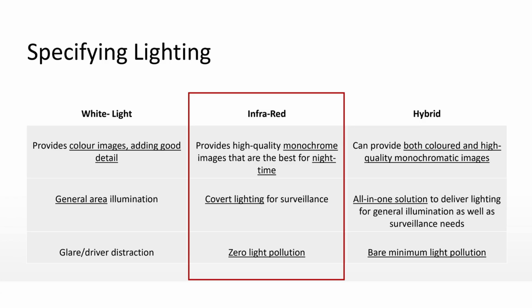And so you'll often see about a 50% drop off in terms of usable distances. However, where this comes into play is, of course, applications where no red glow at all can be required or allowed. So, for example, we'll commonly see this in train line type applications where the red glow, even just a very faint one, could be construed as a warning signal. Now, some people get around that by using 850 or lower wavelength lighting, but using it perpendicular to the track, for example. But that doesn't come under the scope of this particular presentation.